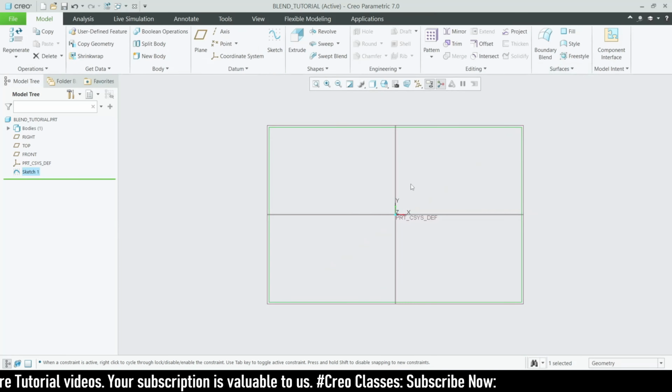This is the same thing as the extrude also, right? You have to mention the height, like whether you want a height value of, let me just say, 500. If you have a value of 500, this will be extruded up to 500, but you need to mention the top profile, how you want it to look on the top face.